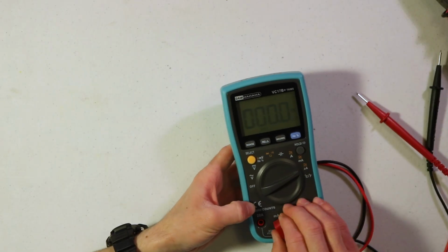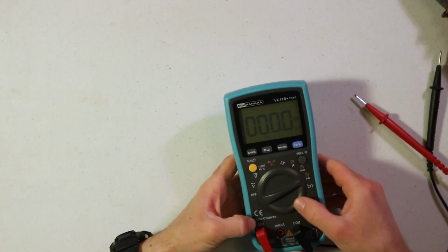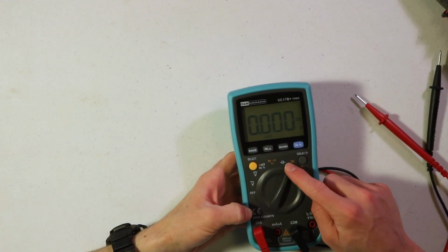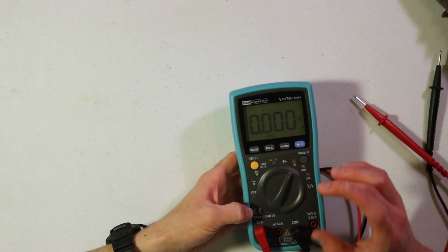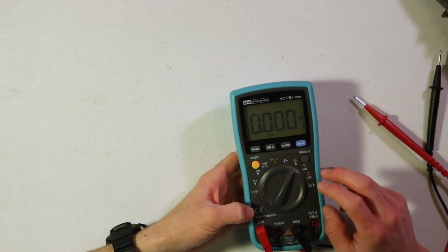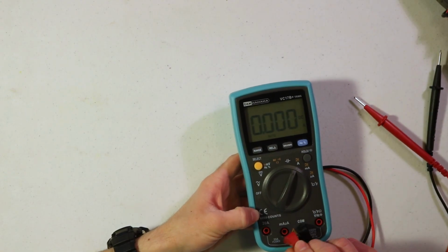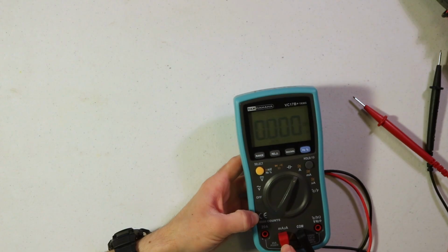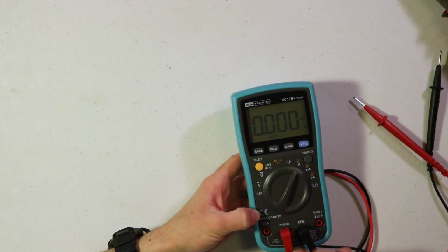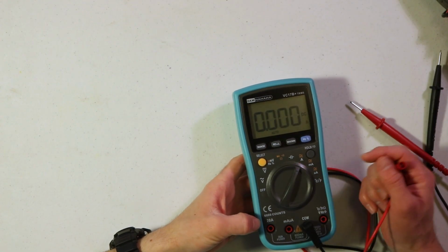And if I wanted to measure larger currents, then I can move this over here, plug it into the 20 amp port, and then turn this over to amps. And depending on what your multimeter has, these ranges are not going to be the same. They may be numeric ranges where maybe it's 0 to 500 milliamps or up to 2 amps or whatever, but just select the correct range on the dial and then put your probe in the correct port. So for most of the things that we're going to be doing, you'll be wanting to have it on the lower current rating, but just double check and see, if you're expecting something higher than what it can handle, then you definitely want to put it on the higher rating and select that on the mode dial.